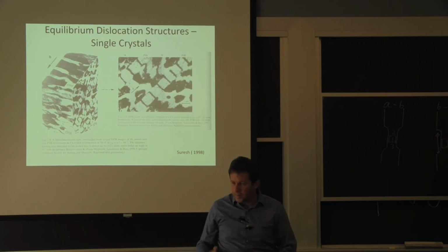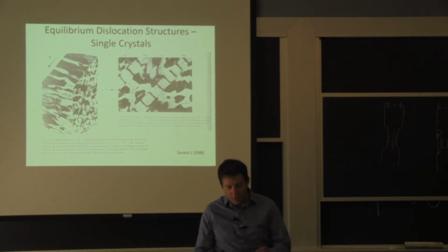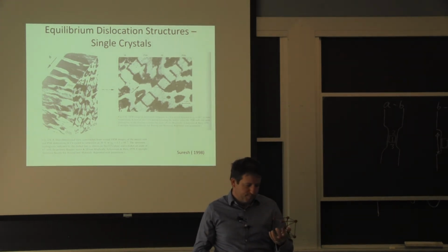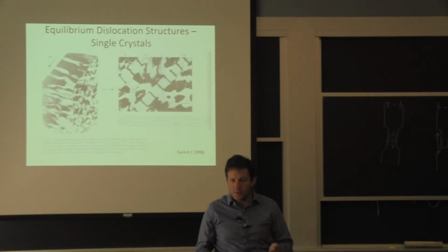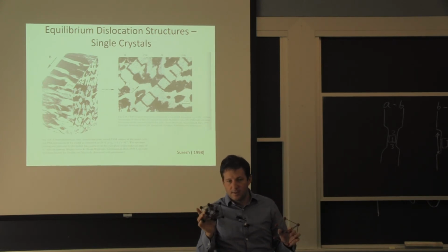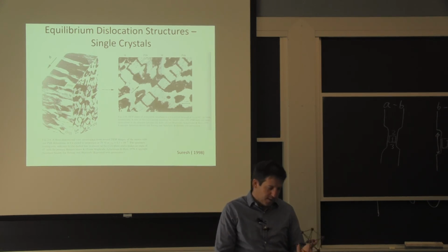That's really how the structure comes to the natural disorganized state. Now, I brought these because you asked me the question between steel and copper and aluminum. The steel that we know at ambient temperature, we're not talking about stainless steel, we're just talking about a pearlite, a normal structural steel, has this microstructure instead of the black pieces here for copper and aluminum. So you have fewer slip systems in a structure like this than you have here. The high density planes and directions, you only have 8 here and you have 12 there.